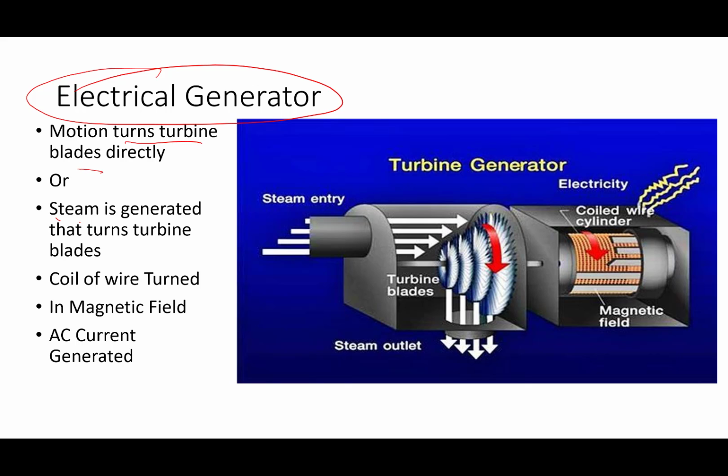Whatever kind of electrical generator you are dealing with, you're going to have big turbine blades. Now, if it is a steam-powered generator using one of those fossil fuels or nuclear power that's going to generate heat, I don't care if it's a nuclear reactor or a coal-burning plant, it's nothing but a big fat tea kettle. It is being burned to make steam, and the steam is sent through to rotate those turbine blades. You just want kinetic energy from that moving steam, and that steam is going to rotate those turbine blades.